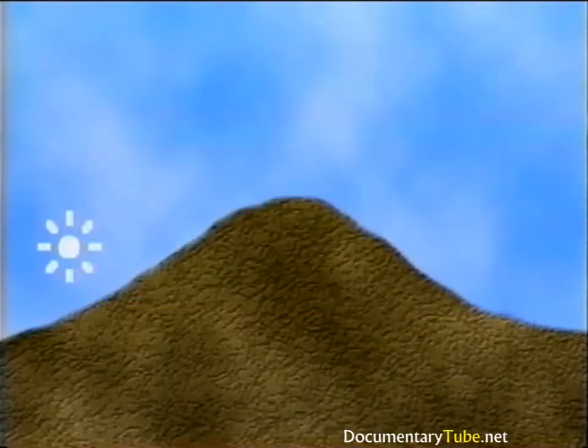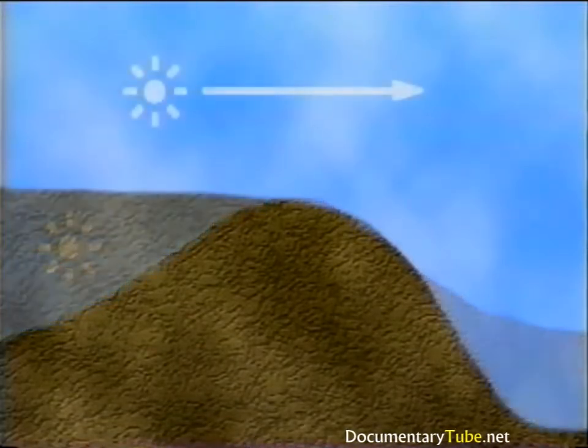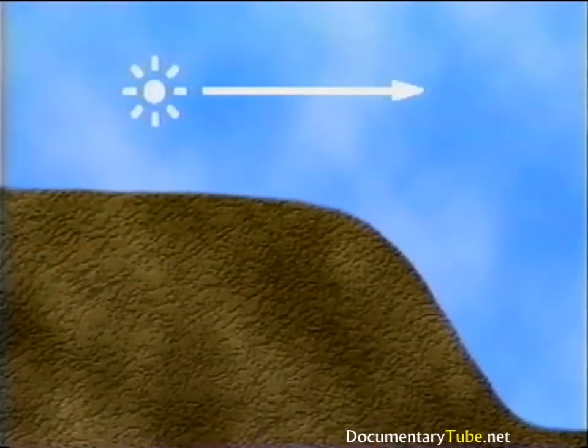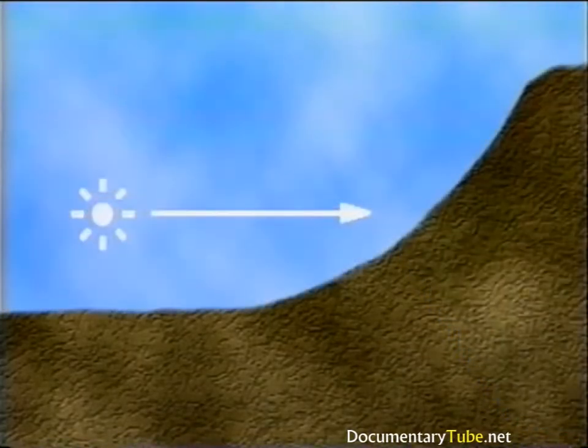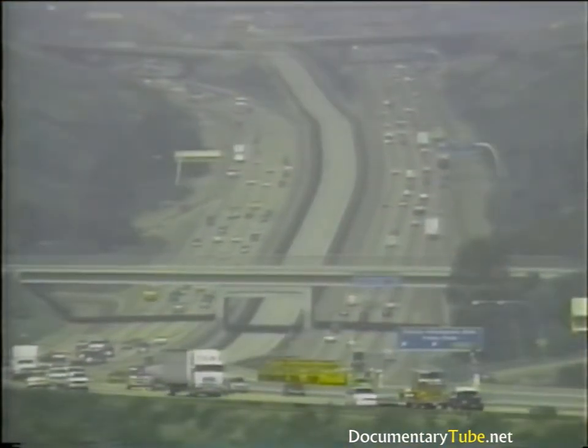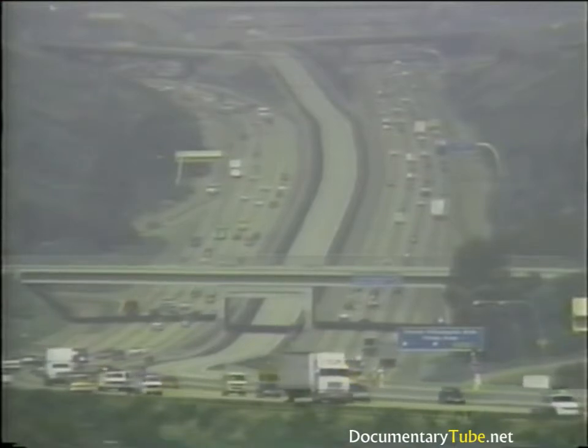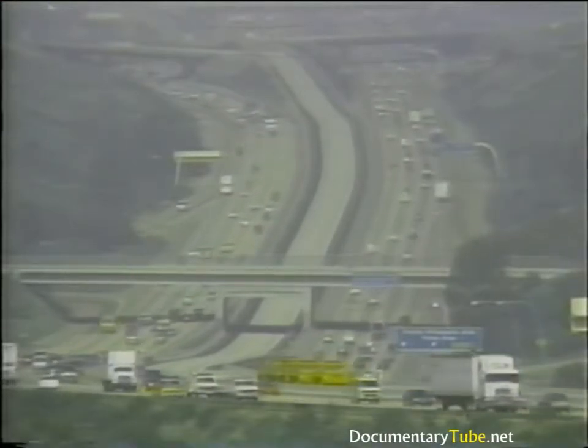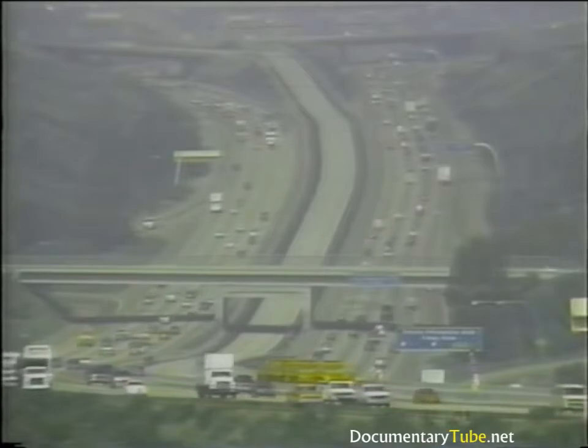Another consideration when discussing ground reflections is the terrain geometry. Sound may encounter terrain that's not flat, but rather terrain with small hills. For a downwardly curving ground, the sound rays stray away from the ground's surface. For an upwardly curving ground, the sound rays are forced to encounter the ground's surface. We have so far discussed several aspects of the sound propagation path, and have now arrived at the last topic covered in this presentation: obstructions in the propagation path.